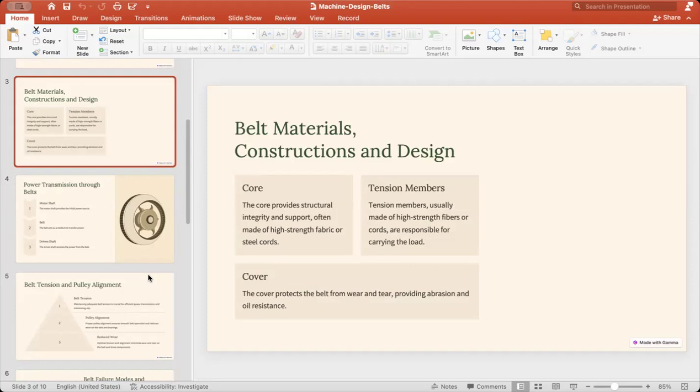The advantage of a V belt is that it cannot come out of the grooves. We also have the wedging action that permits a smaller arc of contact, and a shorter center distance can be used. The gripping action results in lesser tension. These are quieter than flat belts at high speed, and the drive is capable of absorbing high shock, with better initial installation and replacement.